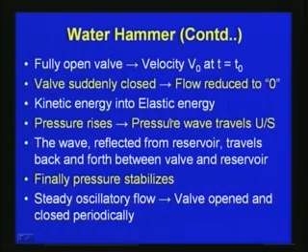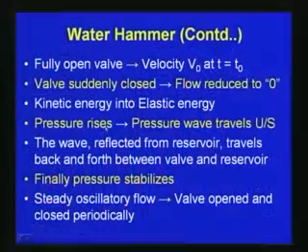Due to sudden closure the flow is reduced to 0, and with the movement of the fluid there is kinetic energy. Due to the sudden closure this kinetic energy is transformed into elastic energy, the pressure rises and a pressure wave travels upstream.